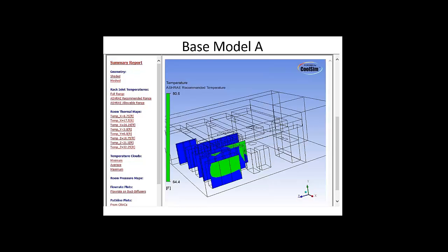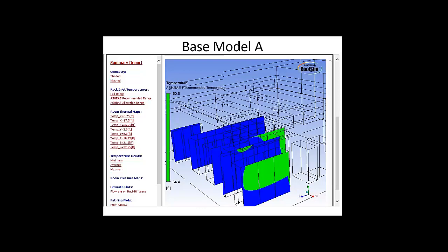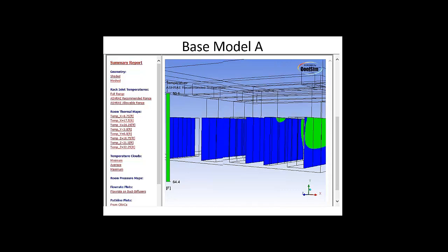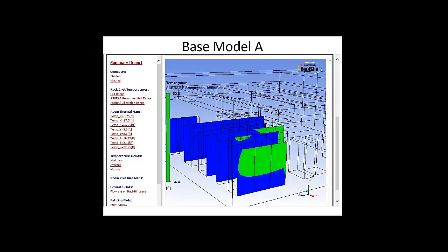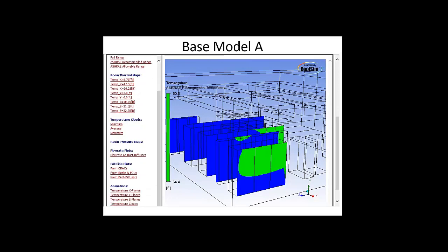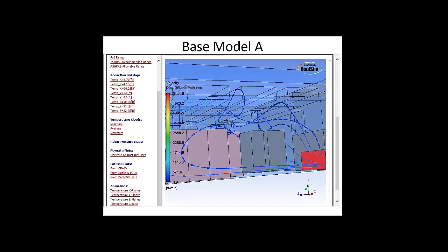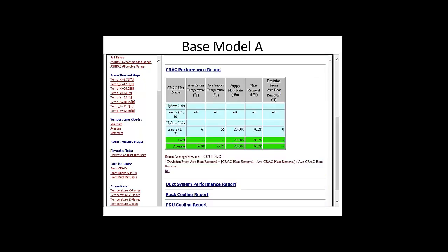There's also a number of plots, but they're fairly straightforward. This one is a conformance plot. Here I'm looking at temperature as it conforms to the ASHRAE spec. There's the spec right there, 64.4 to 80. And you see it's actually failing. It's too cold. These are just the inlets. Some of the rack inlets are supplying air too cold. Other regions are okay. That's because there's a tremendous amount of air swirling around in this room, coming from the cooling units and down and just swirling everywhere.